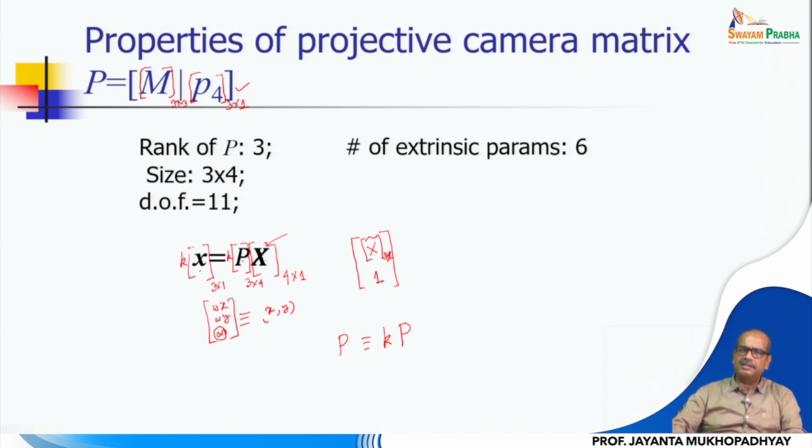Now, though these constraints are there, we understand that several transformations can provide me this kind of configuration. So, for those parameters in the imaging system, in the camera itself, to make it more general, we have to consider what the deviations from those assumptions are. Each one has to be taken into account for a general situation, such as the offset of the principal point. That means the origin of the image plane could be flexibly defined. It is not necessarily on the principal point, which is the point of intersection of the image plane and the optical axis.